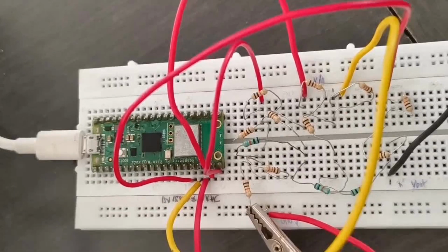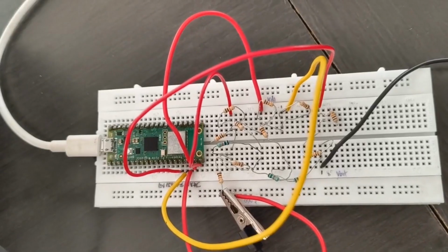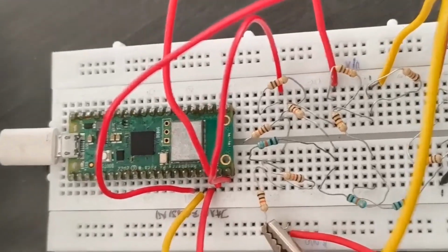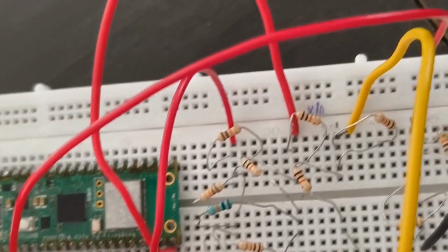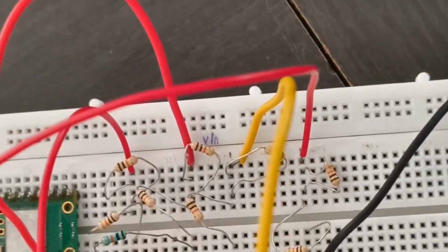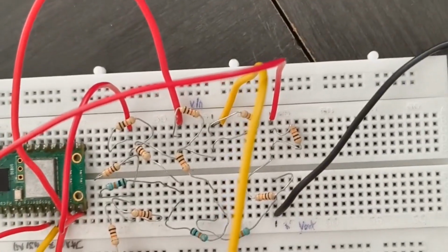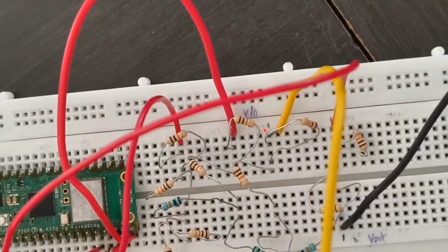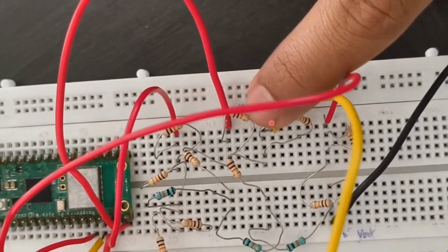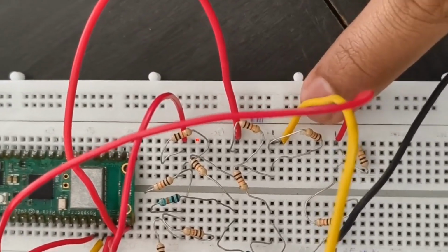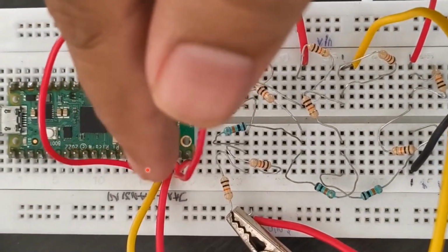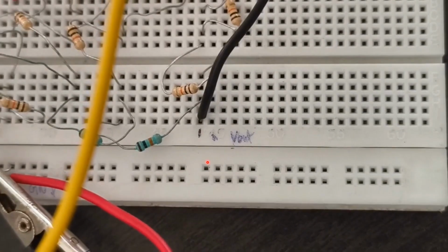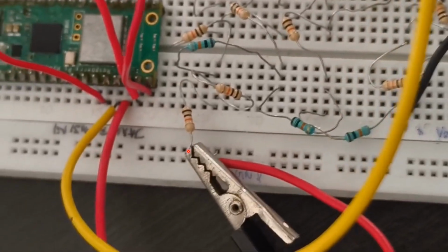So I'm playing this video. You see the configuration of the DAC that I have connected using R2R connections, and you can see the inputs where I have connected the digital pins. You can see small marks over here and here, and then there will be another one here and the other one on the other side. So you have 4 bits connected to the GPIO, right? And then this is where I'm taking the output at this part, and here the ground.